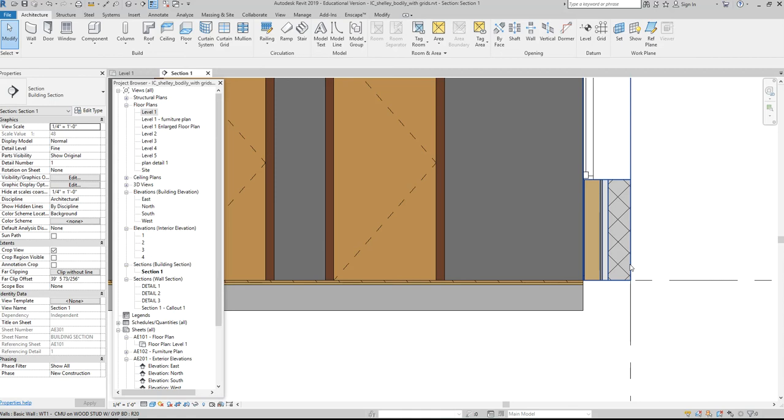So the way that it's usually represented now in Revit is not really very accurate. Your floor doesn't just come in here and rest nicely on nothing, unless you could have a hanger, of course. But usually it extends into the wall a certain amount, until it hits the plywood, drawing a nice crooked line, and then the plywood comes down and covers that, and then you apply your finish. So my point with this is that when you're placing your floor, you want to pay attention to where the floor boundary is.